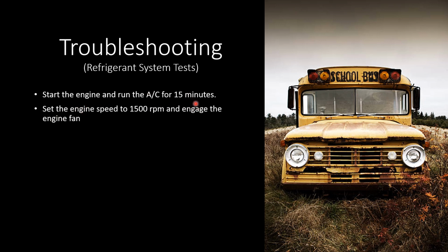So if you could engage the engine fan using your computer, leaving the fan on, that's okay. But just raising the engine RPMs is going to raise the heat, and it's going to raise the pressures, and it should kick the engine fan on.